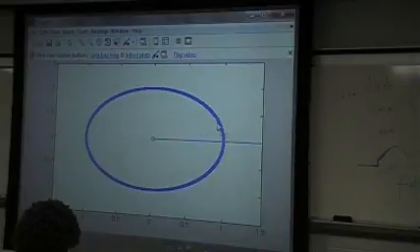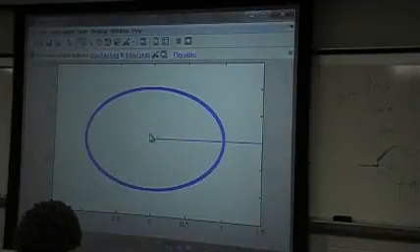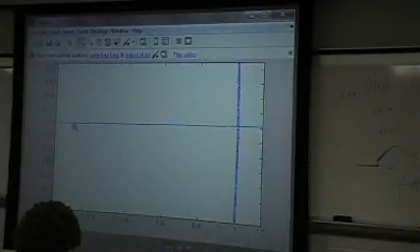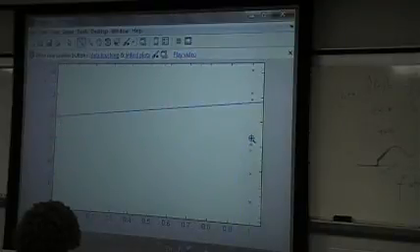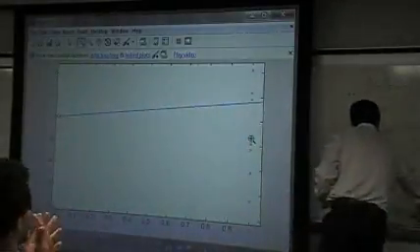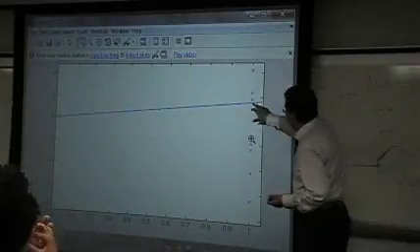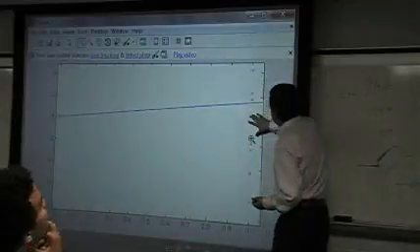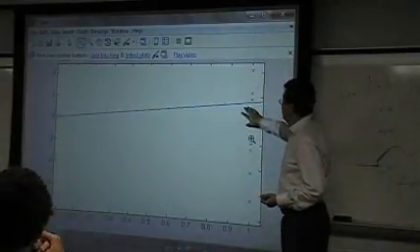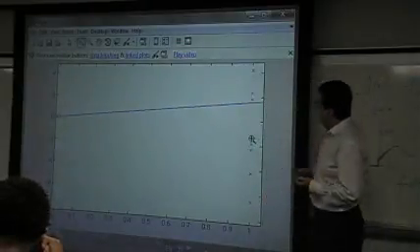And apart from the results, if we go back to the Matlab display, we will have something like this. And these are the poles of the system. The poles of the polynomial, the zeros of the polynomial actually. And if you zoom this part, this is the line for alpha times pi over 2. So you see that in this area there isn't any pole. So the system is stable. All the poles are distributed in the other area.